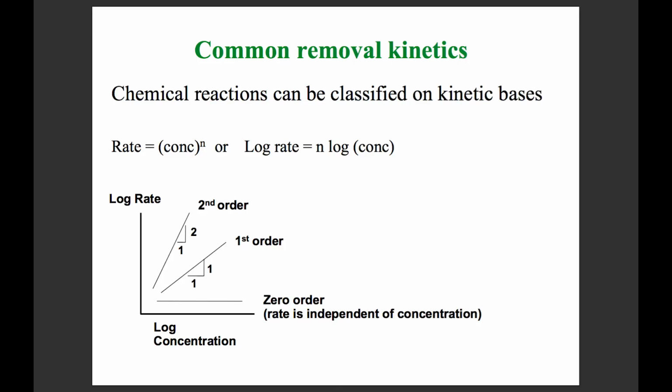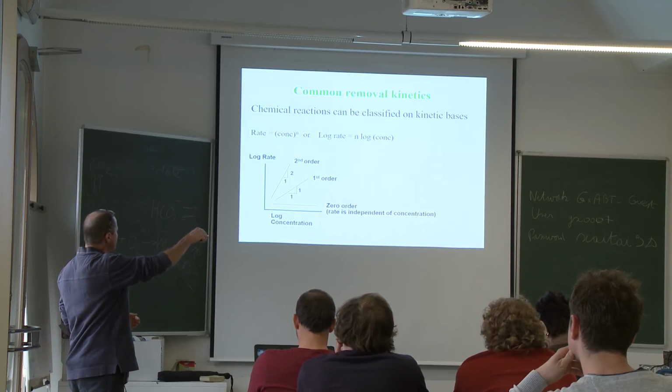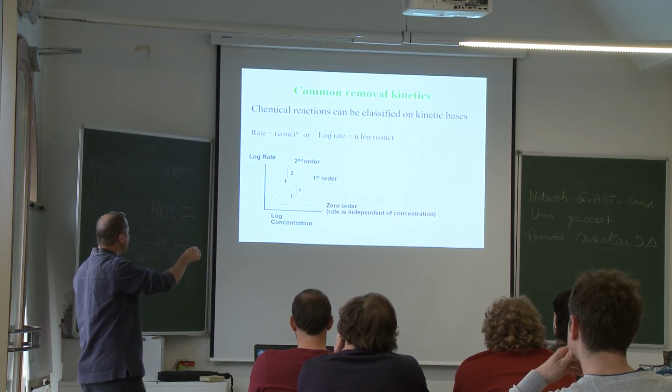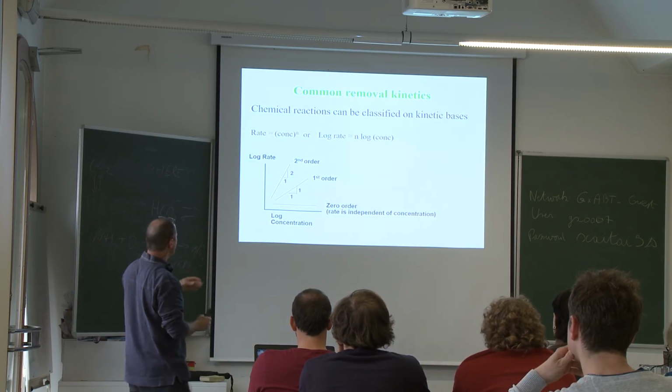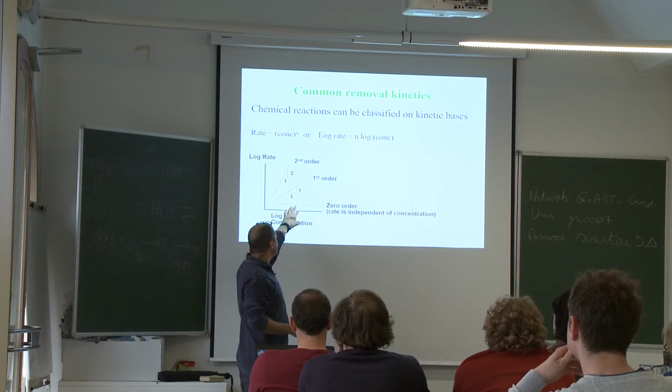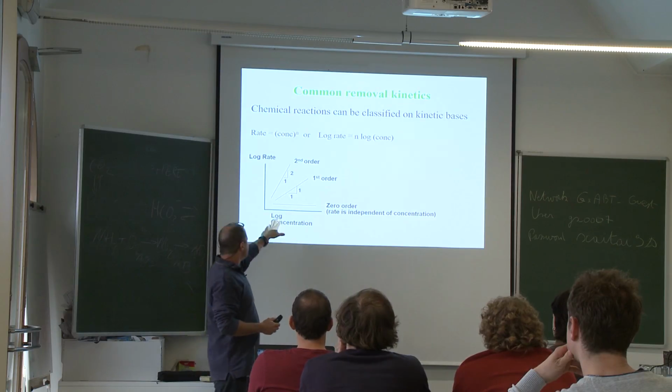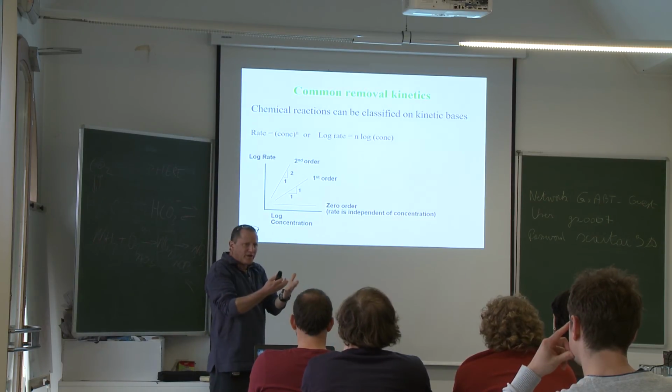Now, the rate at which these bacteria work follows one of several rate processes. Usually it's either zero order or first order. Let's leave the second order aside. What does it mean? It means that the concentration of the substrate, nitrate in denitrification and ammonia in nitrification, affects the rate.